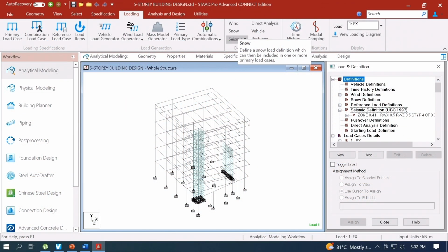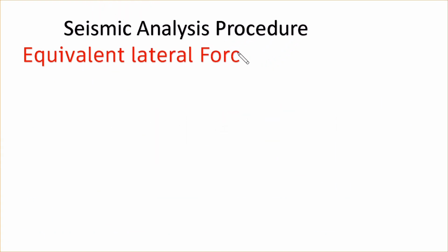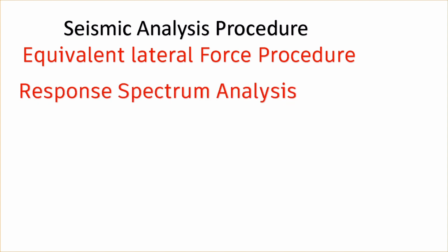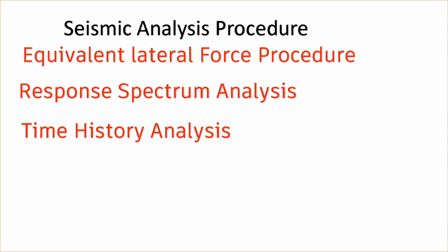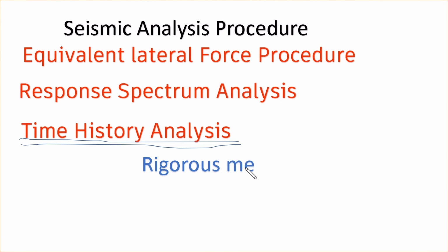Actually, there are three procedures to perform seismic analysis. One is equivalent lateral force procedure. Second is seismic response spectrum method. And the other is the time history method. And this time history method is the rigorous dynamic method of analysis and the most accurate method among the three.